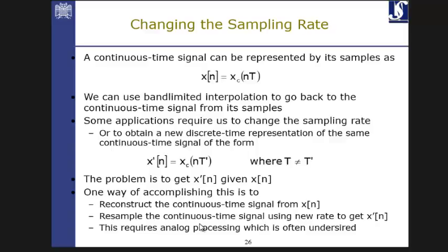And when you say upsampling, it means that, for example, if you had upsampling with the range of 2, it means that between any 2 samples, you add 1 zero. So you add 1 zero in between. That's all. So upsampling by the range of 2 means you have, for example, 0, then you add 0 here, then the next one is 2, then another 0, then you have 1, and so on. That's the upsampling with the rate of 2. You add 1 zero.